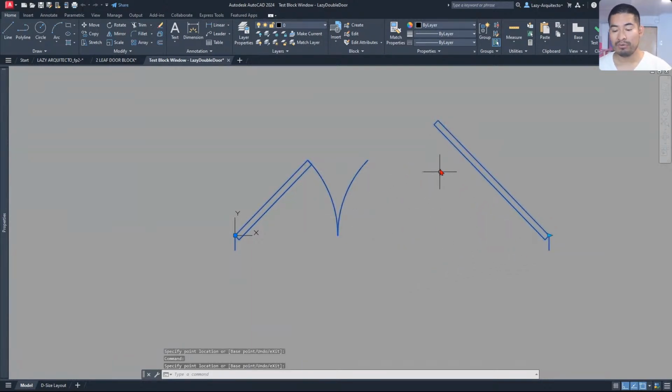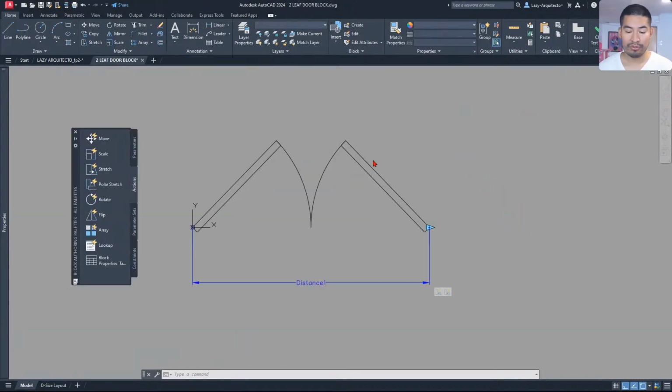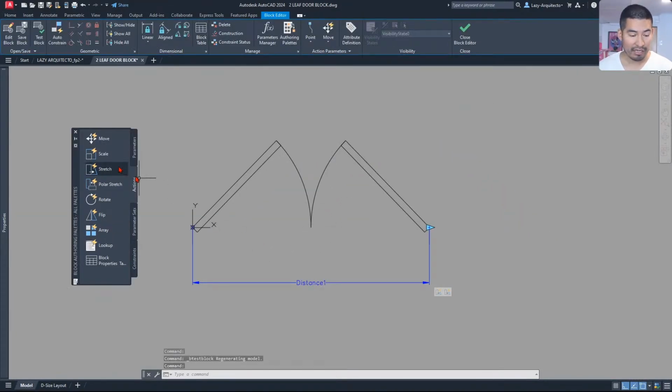All of these steps that we did for this right side of our door, we can also do in the same way for this other side, right? So let's quickly do that. Again, adding a stretch action, and then selecting our parameter, selecting our grip, and then the frame, of course, would be different, would be over here, and the objects will be different also, will be only this door.